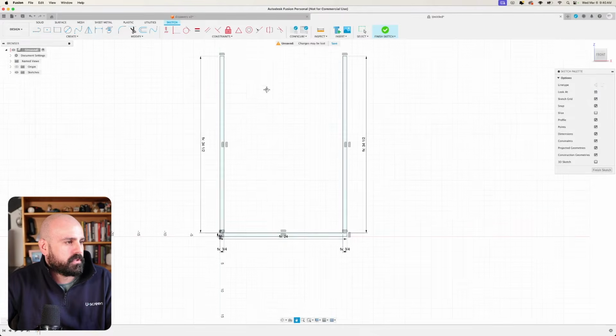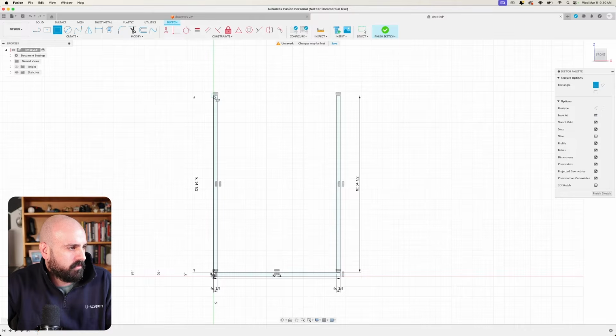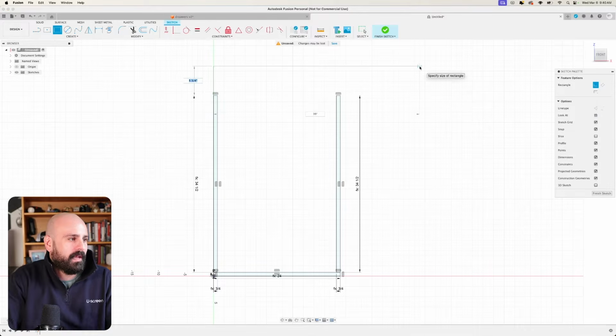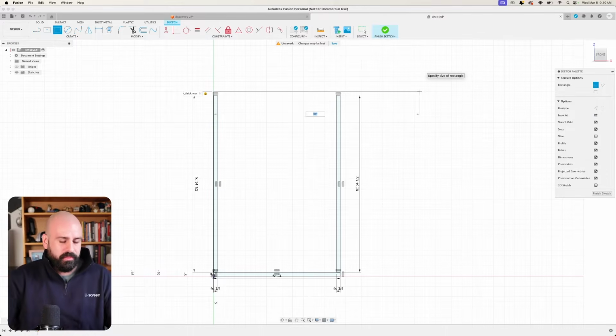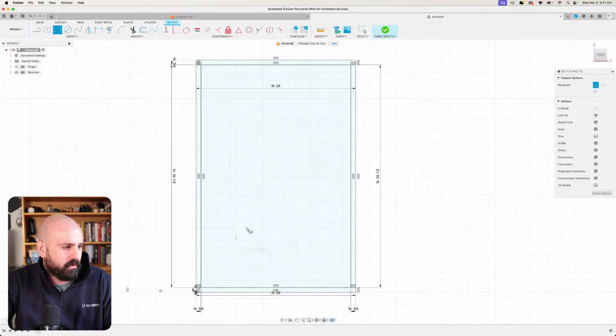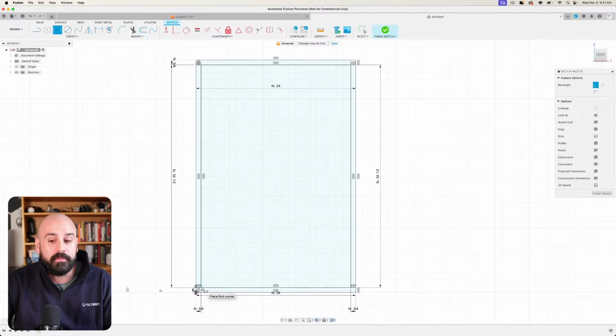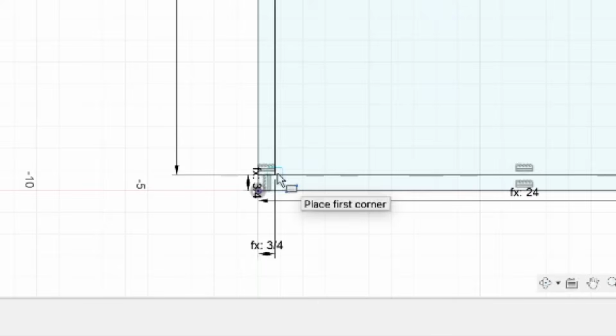All right. So I'm going to scroll up and we're just going to need to add the top shelf in. I'm going to press R for rectangle, grab this corner over here. I'm going to do plywood thickness for this. Press enter, tab. And then the overall width is going to be box width. Press enter. So now I'm going to hit R for rectangle, and then we're going to go down to this inside corner because I want to add in a spot for the drawer slides. So down, click on this first corner, the inside corner there.